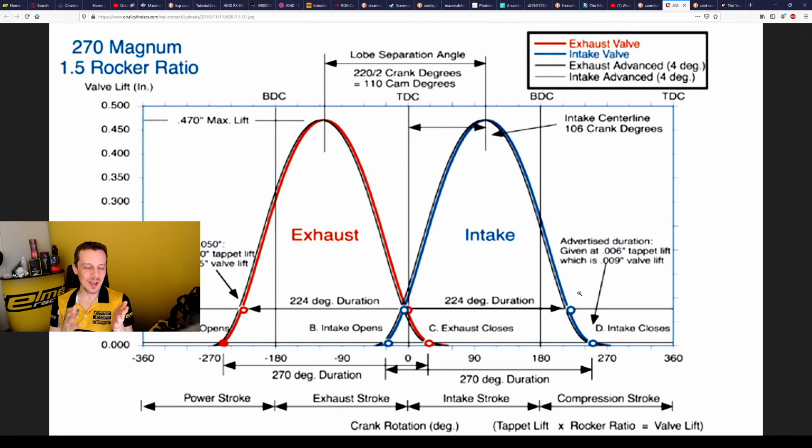Just going really off topic here from poppet valves, but low performance bearing materials are typically really soft, but they are very tolerant of contamination. So if you have engine components fail a little bit, then with really soft bearings, those particles can be embedded in the bearings and you can still run the engine. And that works as long as you maintain the oil film, so that your oiling system is working correctly, and when you have oil feeds in different locations into a bearing, you don't run it progressively dry before the next oil input feed.